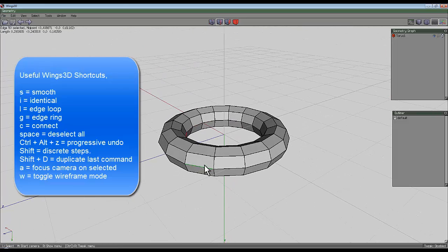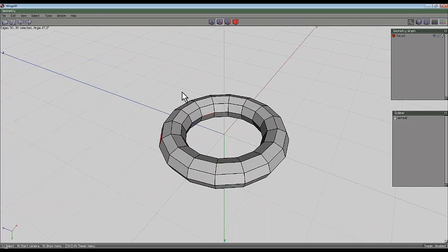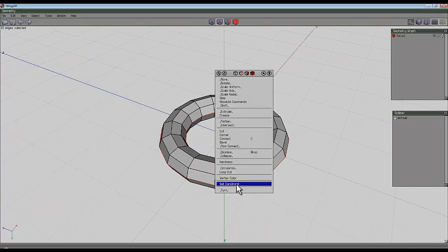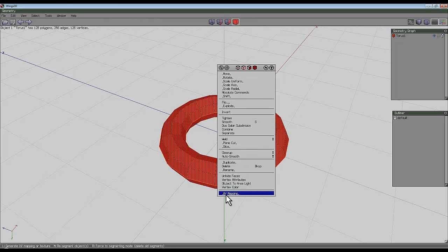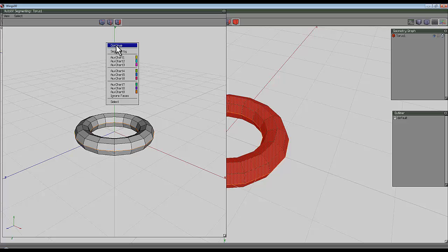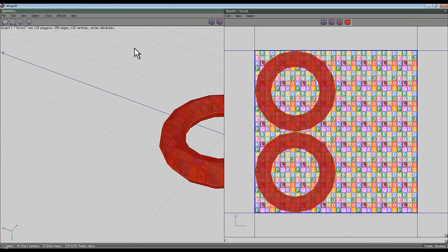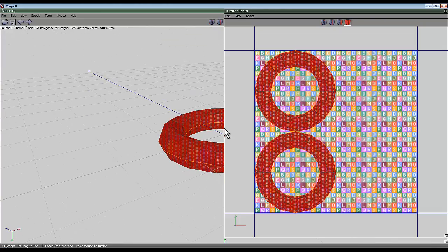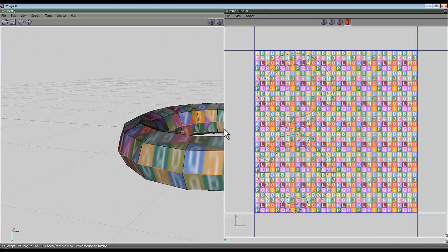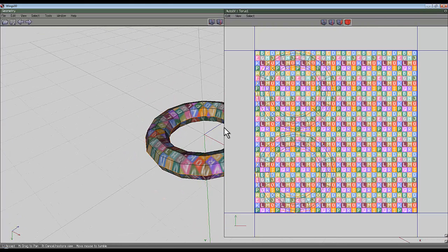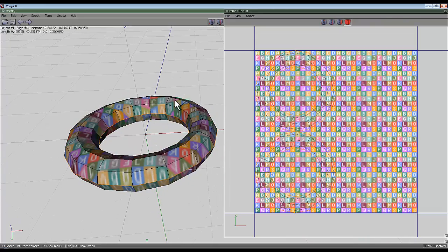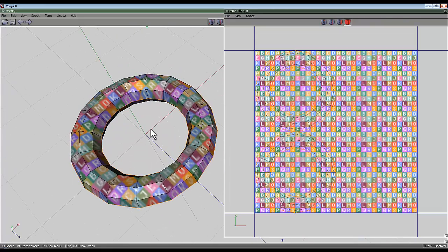So what I'm going to do, I am doing this in the main view. I'll loop set the hardness to hard, and then select the entire object, go to UV mapping, right click, continue by normal projection, and this gives me a normal projection of each of these halves. Now as you can see, there's some distortion on these bits because we're normal to the top, so we're normal on the y-axis. I'll just use the arrow key so we can move this along a bit. So we've projected from above and below.